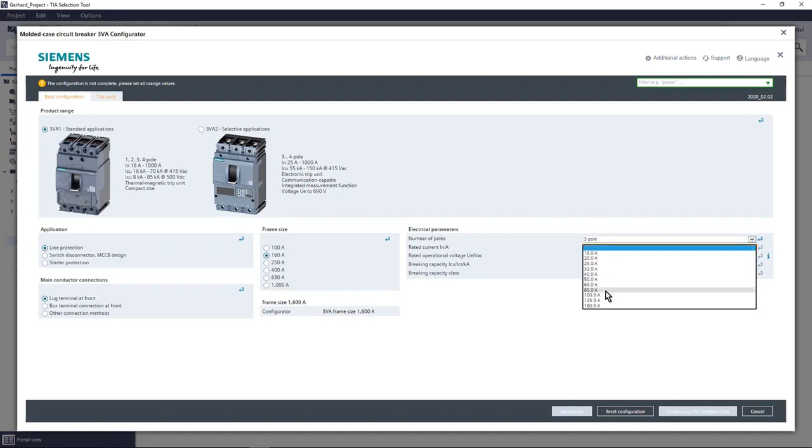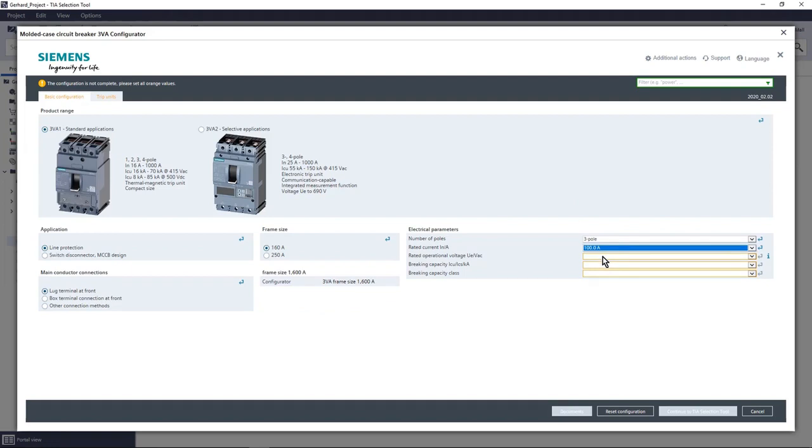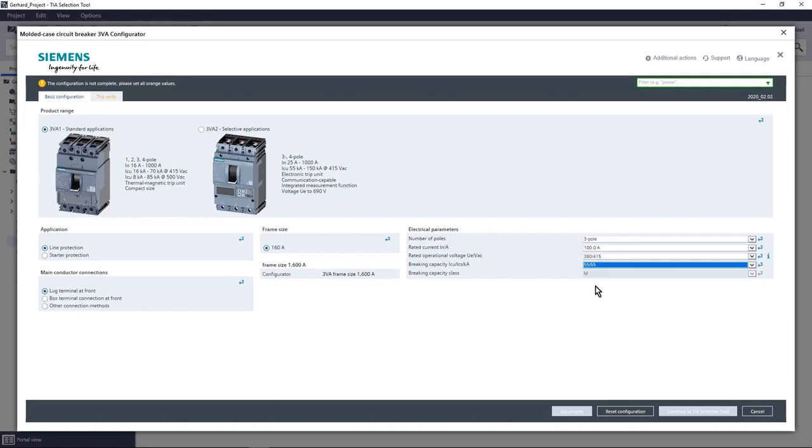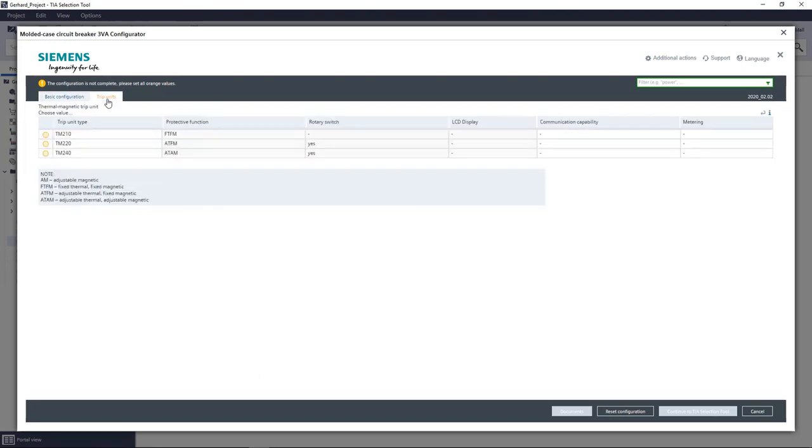All right, so what do we have here? I think I have a pretty standard application. I need a main disconnecting means. I take the breaker for standard applications. Okay, take line protection to protect properly the line conductors, the feeder conductors. A breaker with 160 amp is fine, is sufficient.